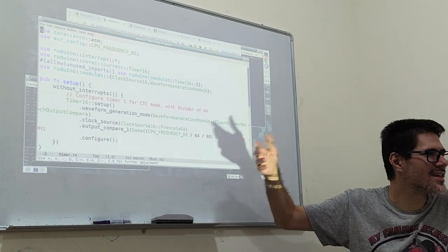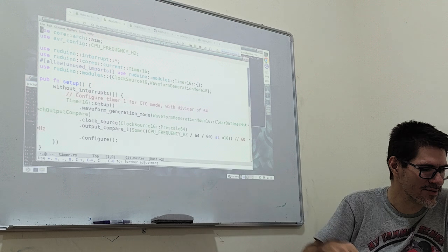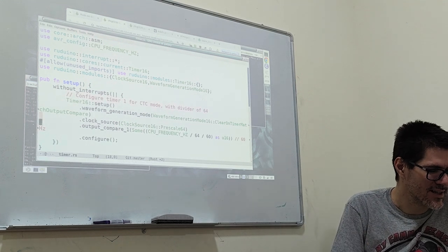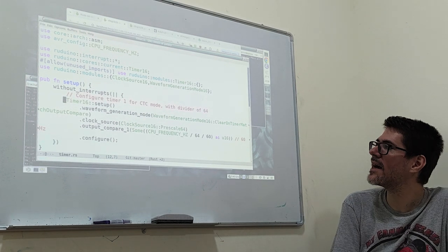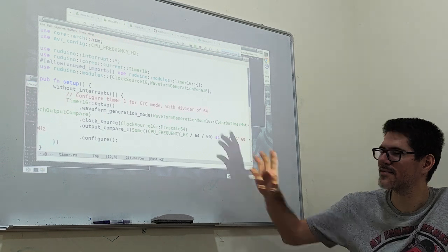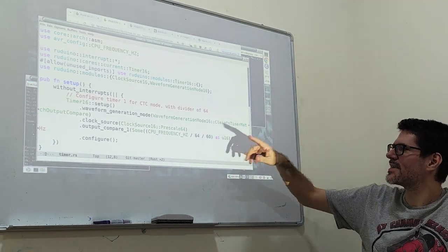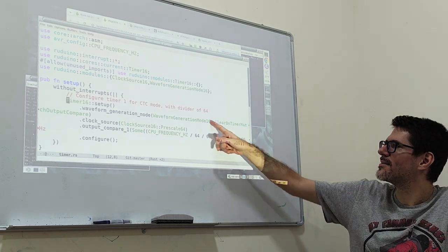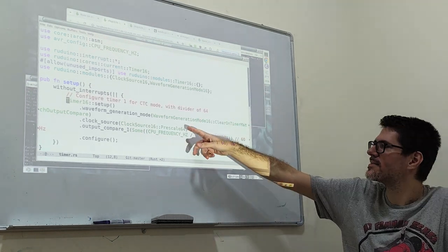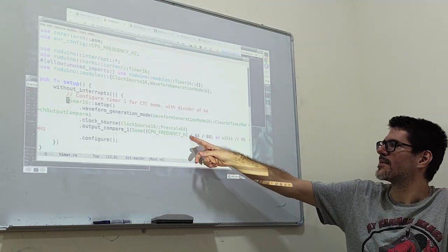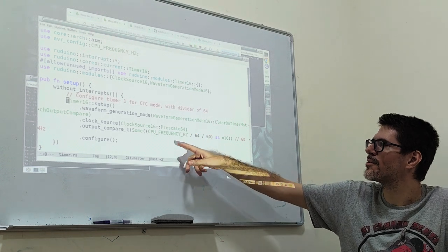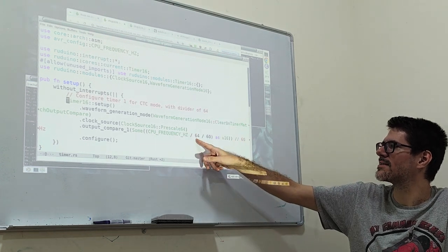But of course, in this thing, there's no such thing, so you have to implement it yourself. So the AVR has timers, and then you can see again using the Arduino library, this is infinitely nicer than it used to be. Instead of mucking around with magic values, you can use nice enums and set it to a prescaler of 64, and then you divide your frequency by 64.